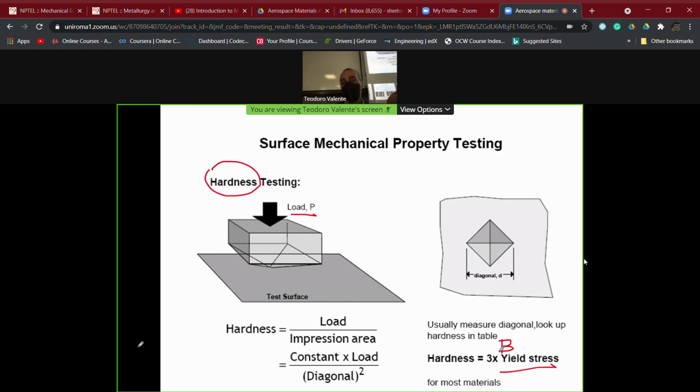But what we must be sure of is that the depth of penetration of the indenter, that is of the plastic deformation, must be localized essentially to the very thin layer if we want again to have an answer which is the answer of the surface and not the answer of the bulk material. And so this means that we need to use proper shape and size of the indenter, but essentially proper loads which are applied.